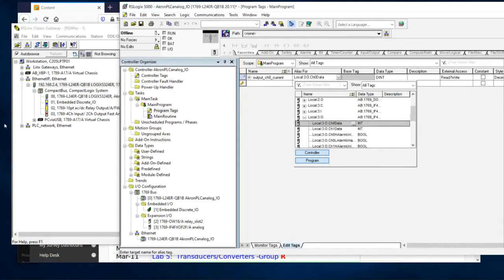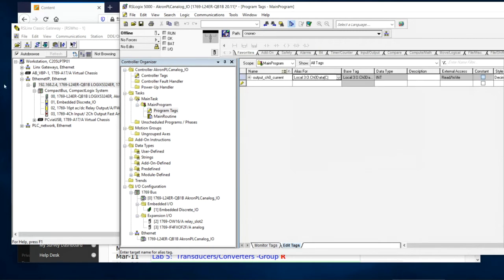Now notice these are integers. That means that they are 16 bits. Those are words. Integers are also known as words. They're 16 bits. Notice you don't click on this and choose 1 bit. It's a number. You have to choose all of it. It needs to be a 16-bit number. Okay, I might even write that down here in the description. This is a 16-bit integer, meaning there's no decimal points. Okay, so it's a 16-bit number.